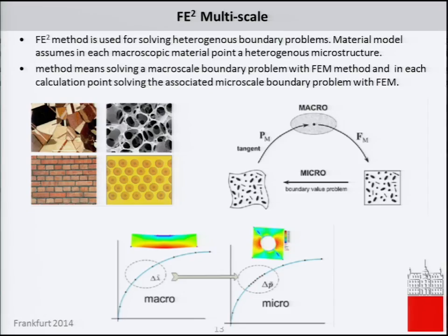The next problem I would like to show is multiscale. This is one of the components of the M5 problem. It's a multiscale problem, so we have to solve the problem at several scales. One way to do that is to make a finite element mesh at different scales. So we have the macro scale, and then we impose the deformation field from the macro scale on some micro scale, and by solving this micro problem, you get average stresses, which go back up.